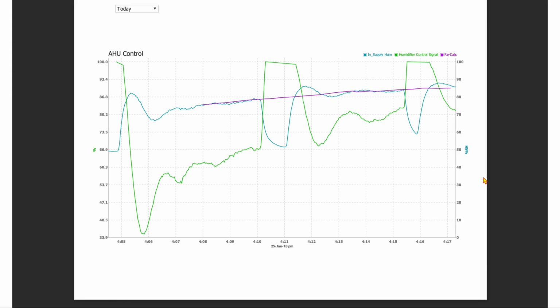So it has three key settings that we're interested in: the P, the I, and the D. So that's proportional, integral, and derivative. So in the vast majority of BMS applications, we probably maybe only see the P and the I being used. Not very common that we see derivative being used, but there's no reason why it can't be. But in this example, this is just proportional and integral.